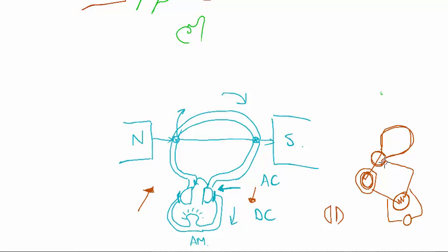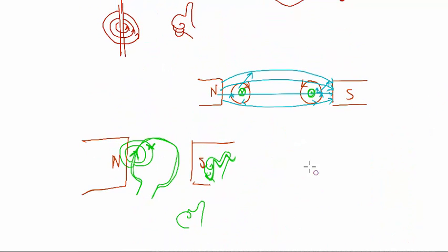Now if you are generating high voltages and you're using a split ring, each time you jump that current, there's a spark, which means it damages your split rings. While here, there's no disconnection. So the split ring creates DC current, and DC current causes damage on those split rings. So it's more costly. It's more cost effective to do alternating current. Also, if I have alternating current, it's easy to then change from electric energy to kinetic energy, because I already have my alternating current. So I don't need a split ring in my motor to turn my motor. So it's also easier to transform.